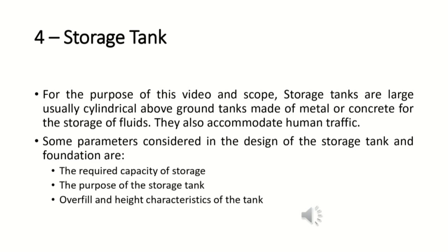These storage tanks, as opposed to the vertical vessels and the horizontal vessels, are designed completely by structural engineers. The metal plates to be used and their sizes are designed by the structural engineer, as opposed to all those other vessels which are supplied by the manufacturer.